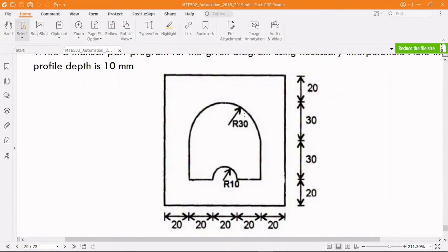To move in this direction is a counterclockwise interpolation, so that is a G03. So that will be G03 X20 Y50, with the radius of 30. So this arc will be created to this point, and from then on you have to change back to linear interpolation, because to move from this coordinate here X20 Y50 back to X20 Y20 down here is a linear interpolation.